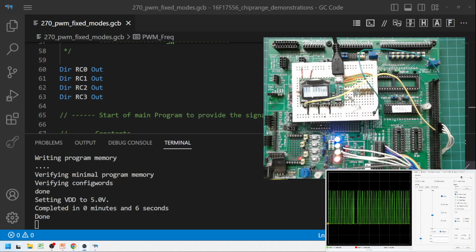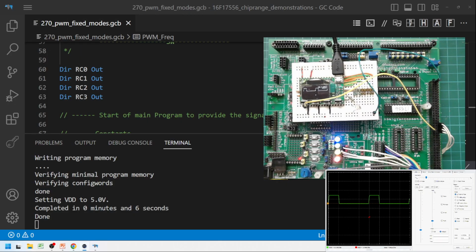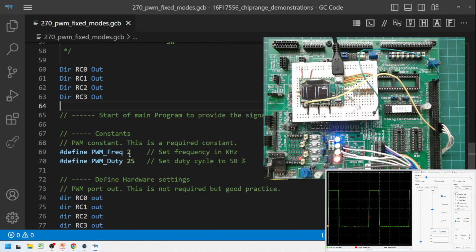Here we go. I'll just do an auto on it. There you go. That's got it. That's just turned on the second channel. I'll just turn the second channel off. Change the position down here and just increase the gain so that you can see it. And if I wanted to change the duty,